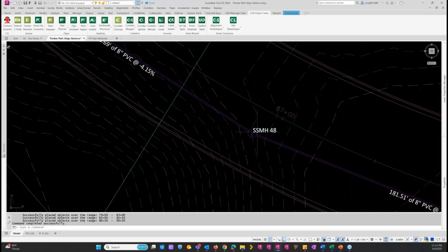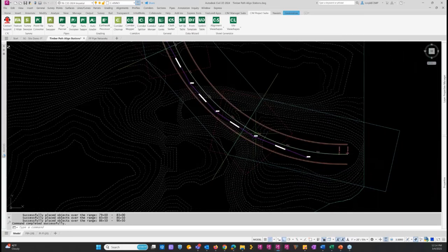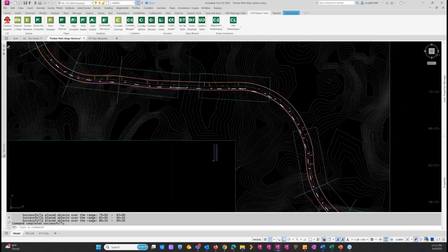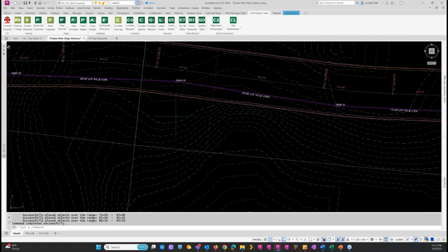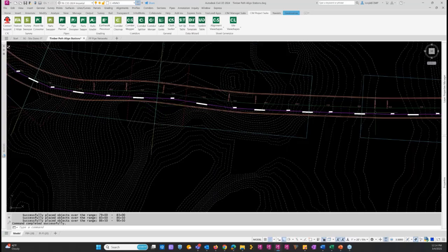So you see right away it avoided that one and rounded to the next whole number that it found, the 50. 50 stations is what I told it to round to. And if we come and look at these, it did that as well. So if there's anything in there that you wanted to avoid, manholes, blocks, there's a whole host of things we can avoid.